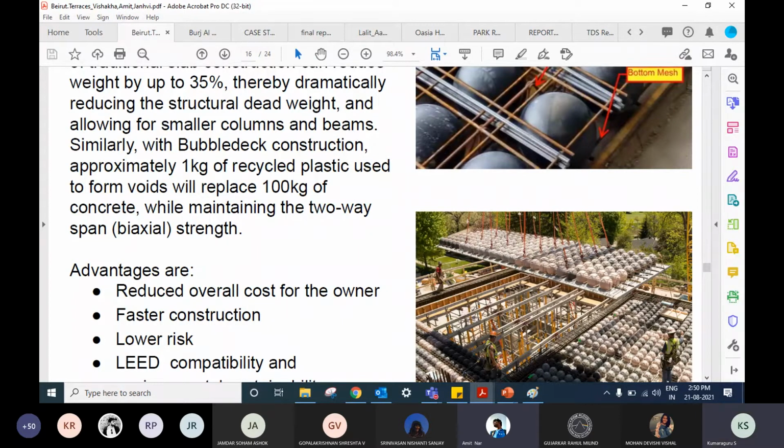Okay, Amit, so what happens in other buildings? Where do they run the cooling system and the services? Yes, there are many other buildings which are done without this voided slab, where they have their services perfectly running not through the slab, just below the slab, and it could be hidden by a false ceiling. And you have some steel beams where they have web penetrations through which some services run.